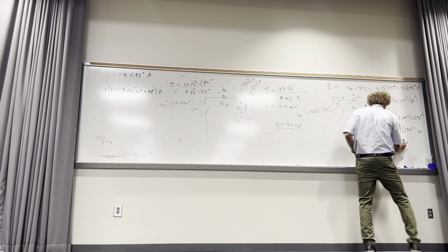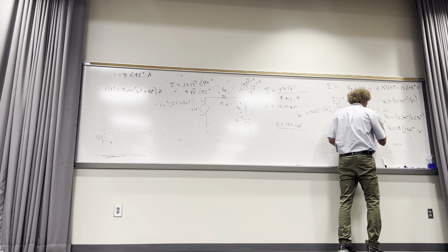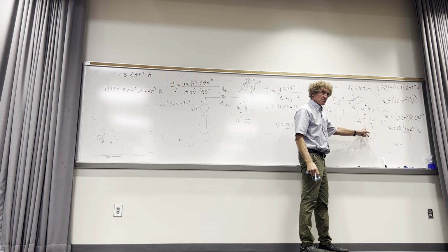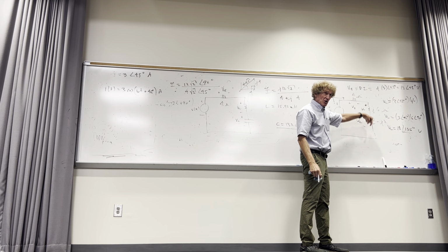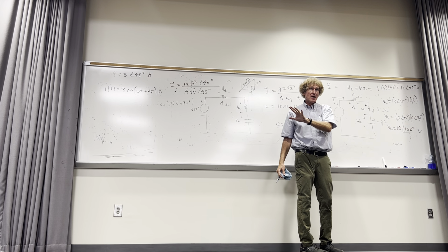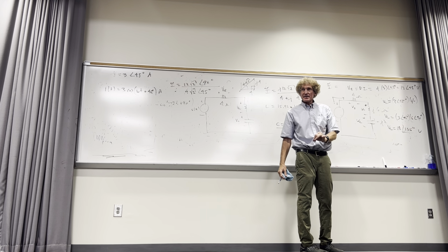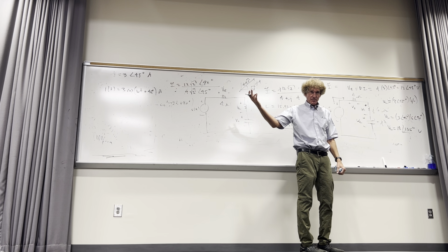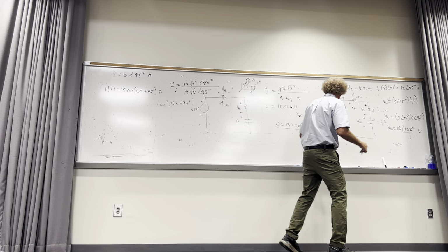Okay? What about down here for this capacitor? You'll notice the sign, plus to minus. So you want the phasor current entering the positive terminal. Do you all follow me? And then we multiply it by the impedance, which happens to be minus J2. Take a moment, make sure you capture everything I'm saying.